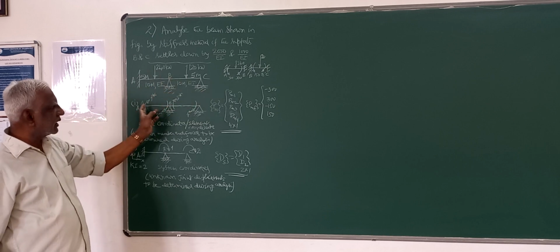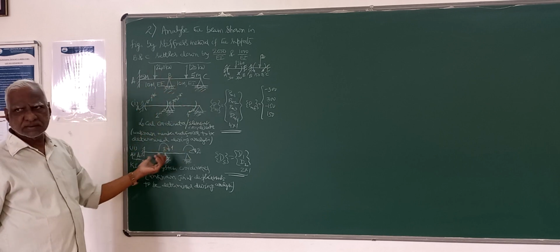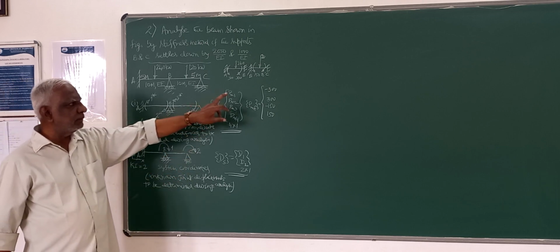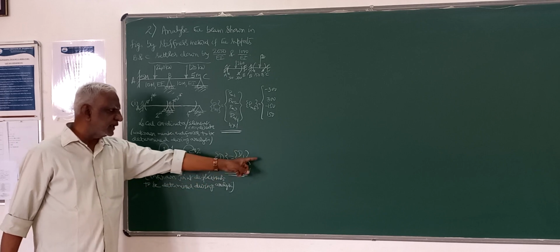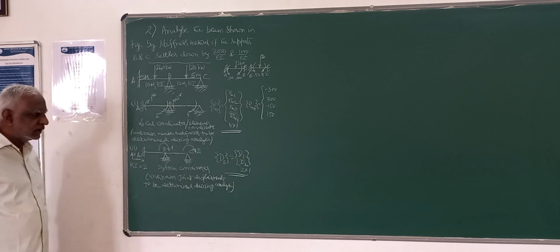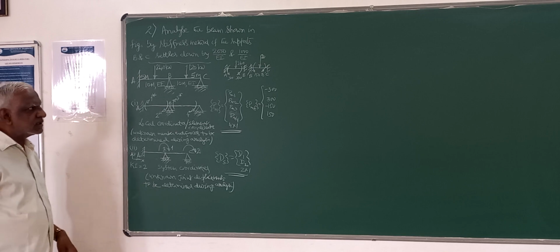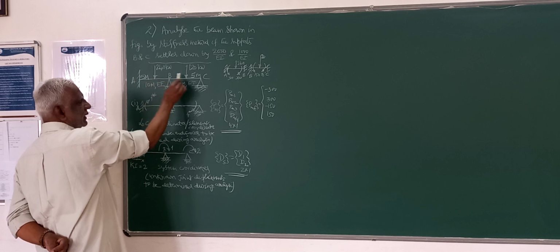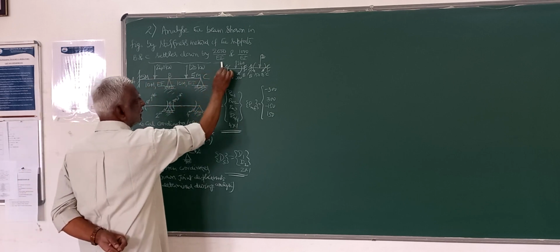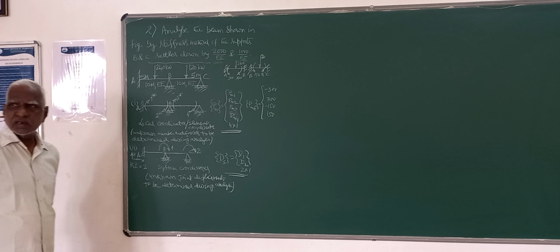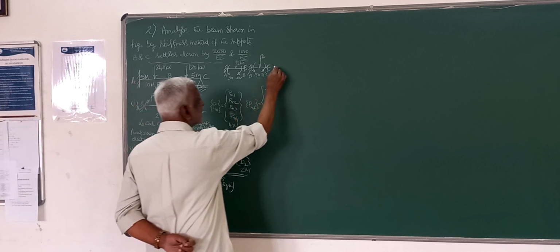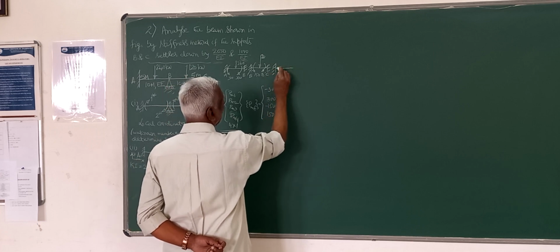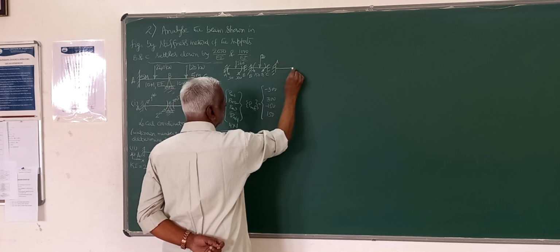The equivalent loads corresponding to the element or system coordinates, that also I am writing. Here I am writing PM, PMF. Likewise, DS and PS I have to evaluate in two steps. This particular problem is not only subjected to loading, but also to a settlement of support. So due to that settlement of support, we have to calculate the moment generated.